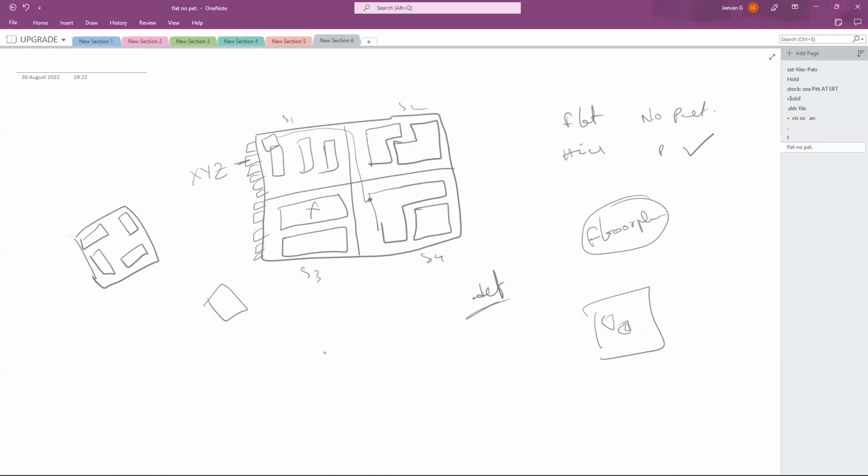Voltage areas means the cells inside this particular area will be working at some different voltage. For example, the entire chip is working at 0.8 volts, but the cells in this particular voltage area will be working at 0.6 volts only. This is a different voltage area, so this is like 0.7, this is like 0.9, this is like 1. I'm just giving an example. The remaining cells, all over your chip or your block, will be working at 0.8.